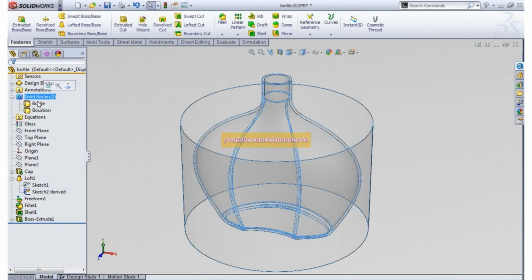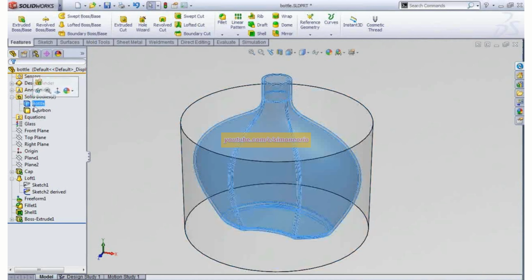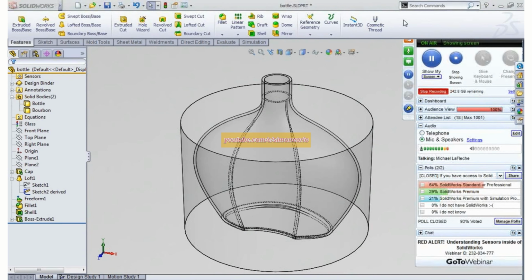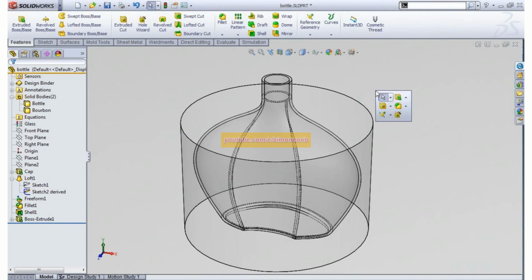So we're in a part file with 2 bodies, essentially, when we unchecked Merge Result. And I rename it here because it makes it a lot easier when you're filling out the next form coming up for using the indent tool, one of the most powerful tools inside of SOLIDWORKS. All right, so I'm going to hit the S key on the keyboard. The letter S pops up the shortcut toolbar, and you notice what becomes available if you're using SOLIDWORKS 2012 is the search commands box as soon as you do that. And I can type in the word indent, and it will bring up the indent tool.